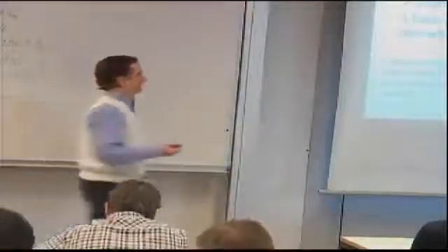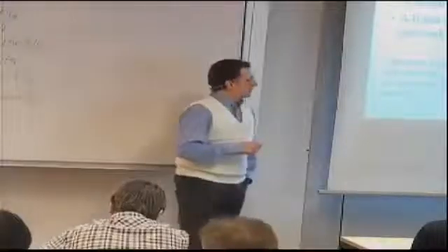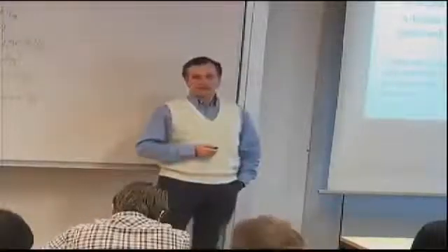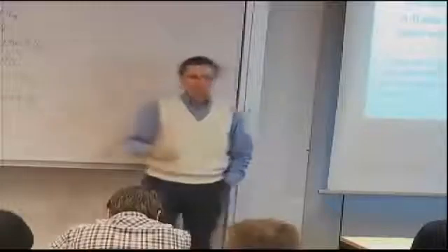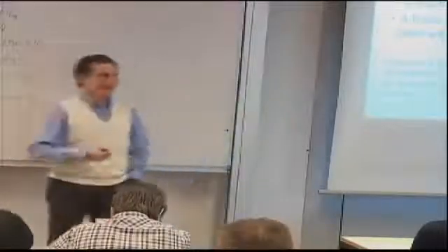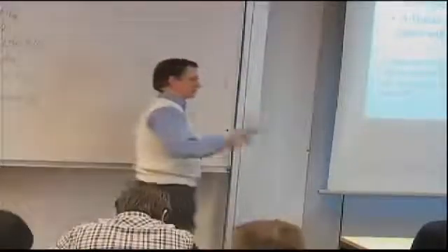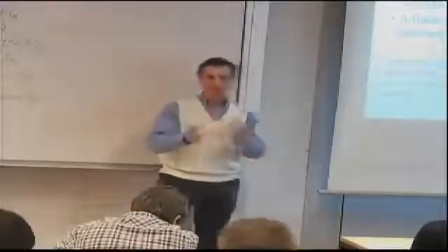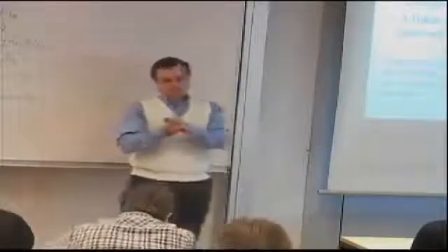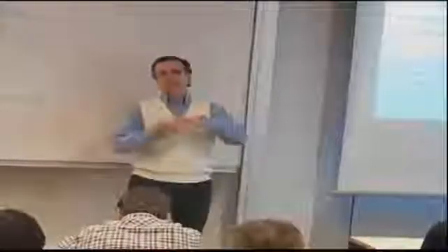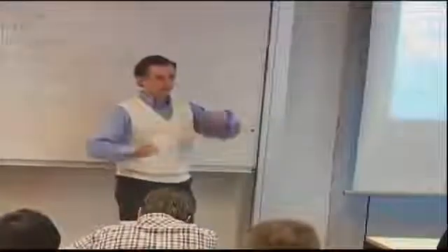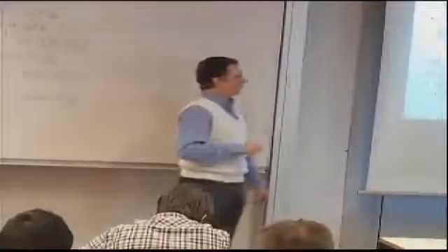Typically, the A basis is used for single load path primary structure. So if it's a blade and you lose the blade, you lose the aircraft, then that's an A basis design. If it's a skin stiffened structure and it's just a local failure, you can definitely redistribute the load, so it's like a multiple load path or slightly redundant structure. In those cases, you would use the B basis. And you will be seeing those in your homework. Environment, temperature.